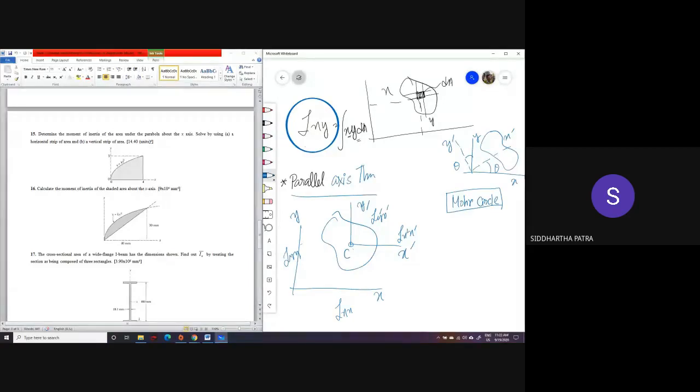Okay. This actually is a universal way of getting coordinate transformation in terms of rotation for quantities which are like tensors. For example, the I tensor can be populated with Ixx, Ixy, Iyx, and apparently Iyx by definition is also Ixy. You see, integration xy dA is integration yx dA also. And then Iyy. Okay. Now this is with area moment of inertia.